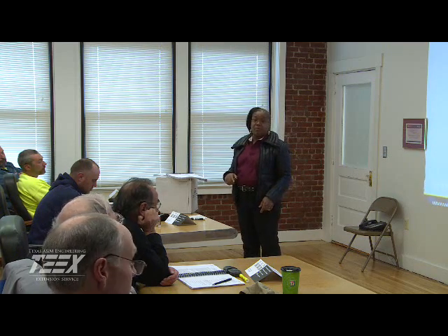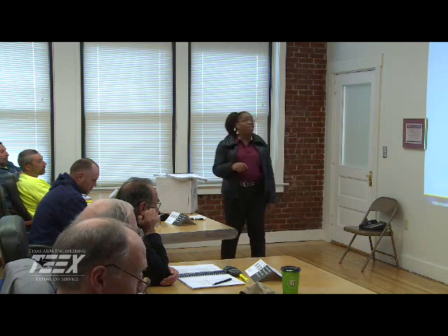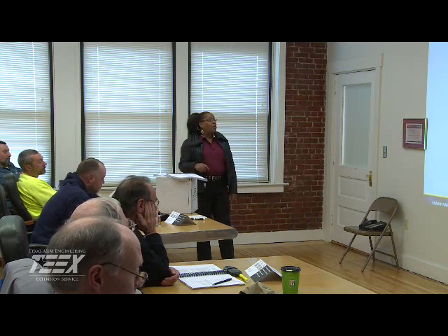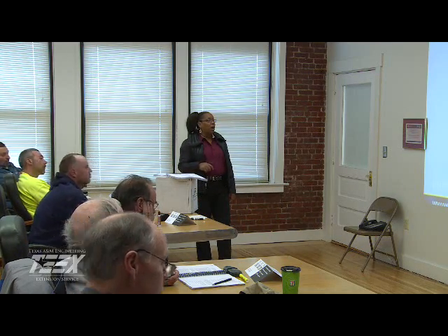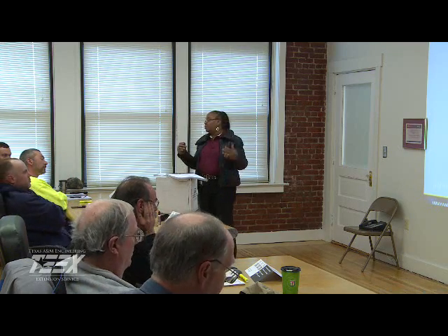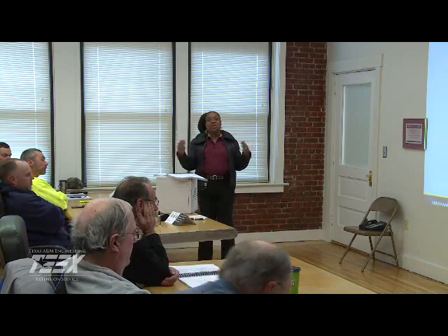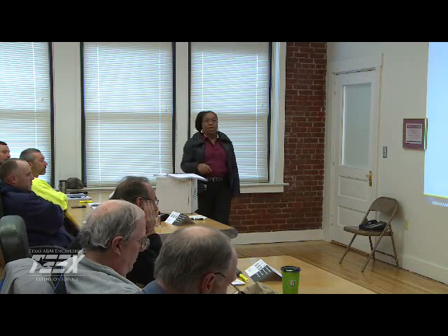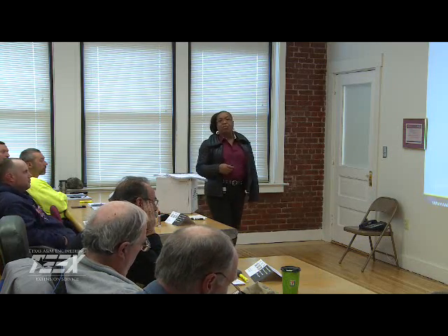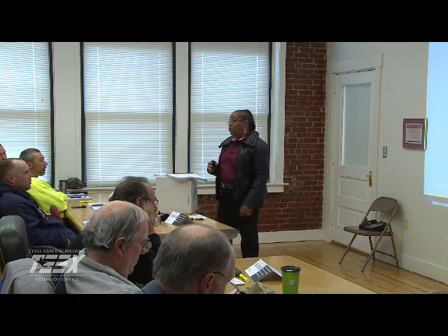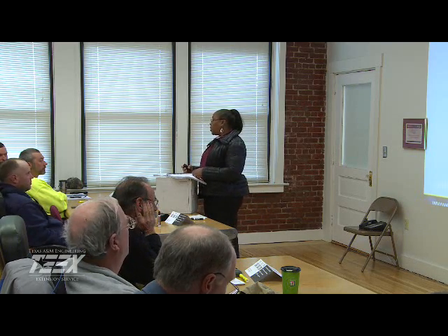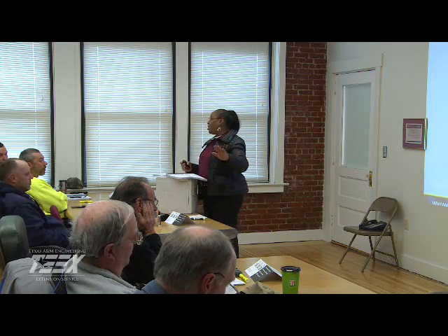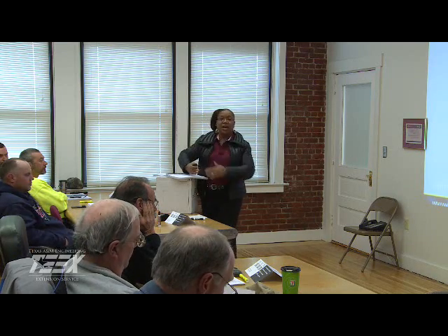All right, you may want to put together monthly monitoring worksheets. This is sort of a plan to keep you straight. It helps to ensure the right number of samples are collected. For instance, if your system must collect 15 samples per month, and let's say Sally Sue is on vacation and Joe Black comes in and collects for the next month, he collects 14 instead of the 15. Is that a violation? Yes.